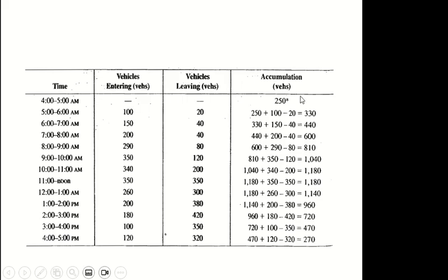So what are these 250 vehicles? These are vehicles already present in the area, usually vehicles which are parked on the sides of the streets, and they could be just any vehicles which are moving around. But they are within the area, so you take a count within the area, and you take it at a time where you know that the outside count will be almost none. There could be maybe 1 or 2 vehicles entering or leaving, but we know that would be very, very low, so we can ignore it. It will not create too much error.